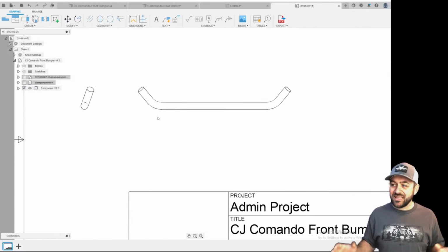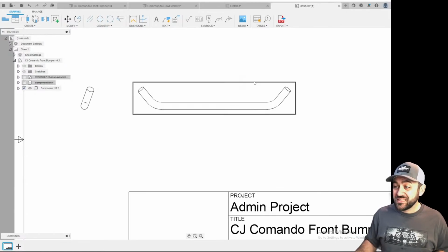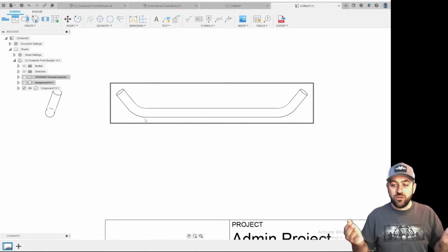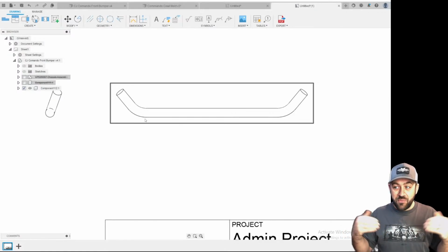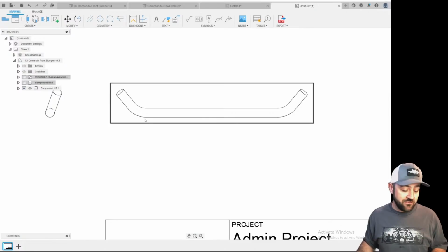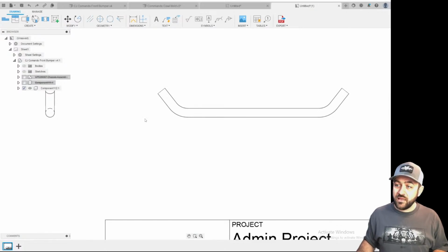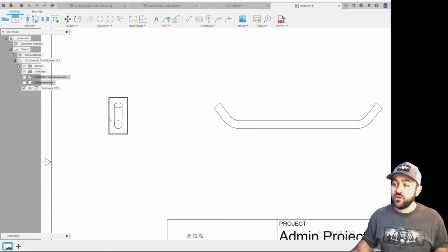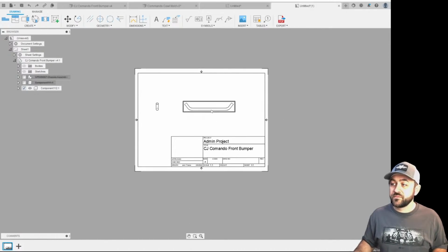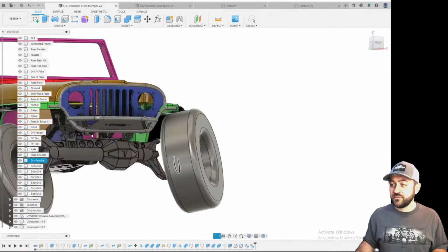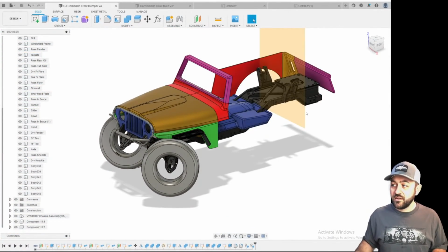So while this looks like it's still a flat tube and it'd be fairly close, your bend radius would not be right, because the further and further this gets up to 90, you lose more and more of the actual bend degree properly. So it's incorrect. This would not give you the proper information. So that is why you need it to be at the proper view orientation to give you the correct template. So that is the importance of 2D drafting in the 3D world.